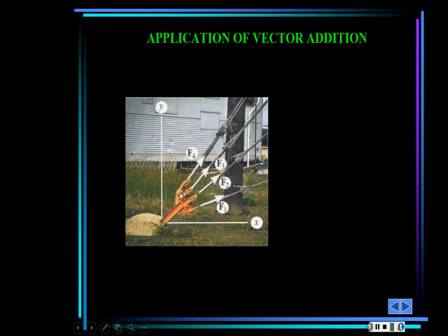What if these bolts here are working in shear? Basically, you have the bolt in this part, and it's trying to cut this piece. It's going to try to cut that part in that section in two parts. What if those bolts just fail in shear? What if these connections here fail? What if the concrete here has sufficient strength, but the adherence between this metal and the concrete, or whatever the base is made out of, is not sufficient?